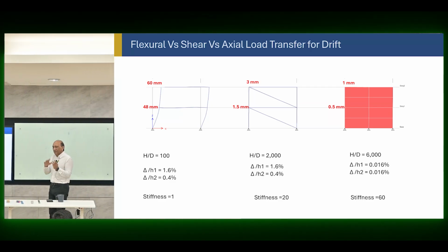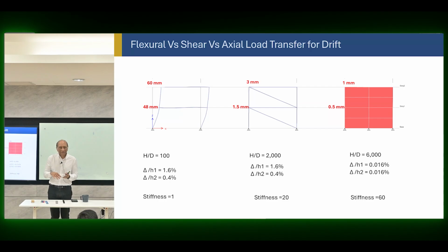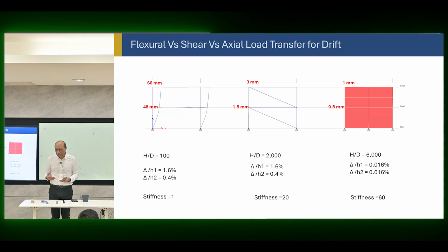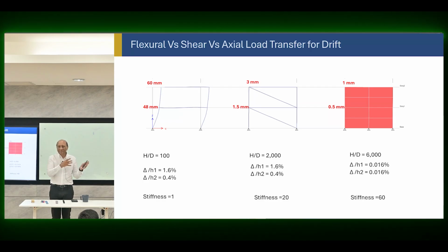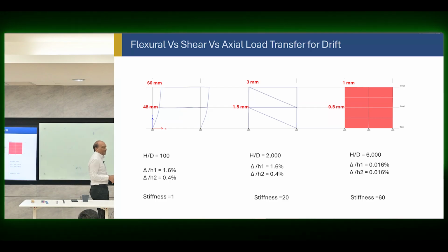So which means shear behavior, pure shear behavior, and tension or axial is interchangeable. And we know it from the previous course, where we remember we converted shear into an equivalent strut-and-tie model. We studied so much about that. We designed the shear based on the tension and compression stresses and forces, which means we know that shear can be easily converted into an equivalent tension and compression system, right?